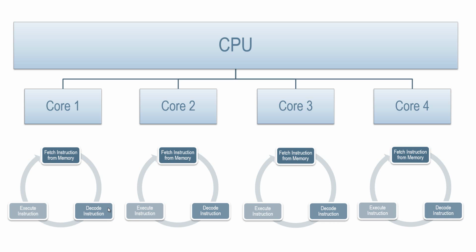It will notice this, and what it does is it almost throttles up one of the cores. Say my CPU is running at, I don't know, 2.4 gigahertz. What it can do is turn the other 3 cores off that it's not using, and then throttle core 1 up to say something like 3.4 gigahertz.